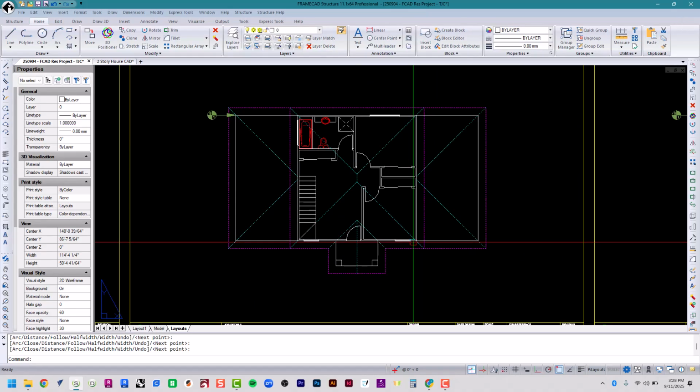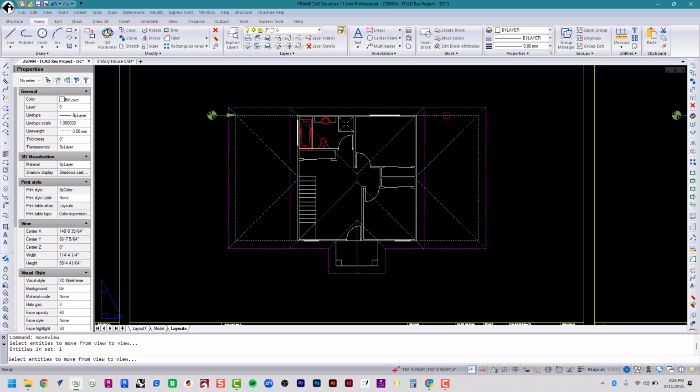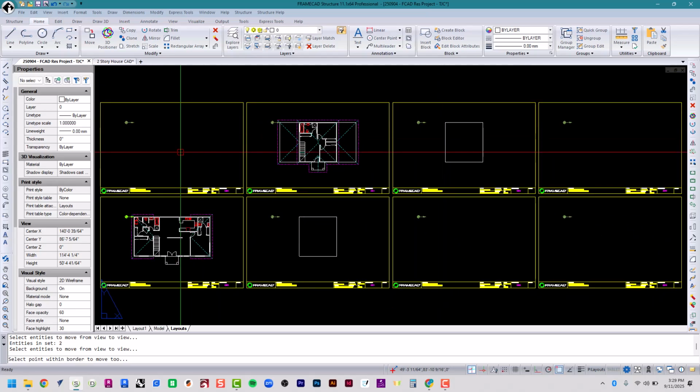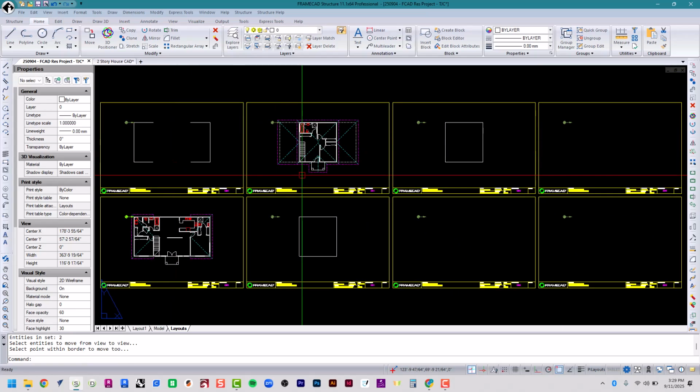Okay. Now the next thing I'm going to do is move view. We did copy view earlier. Now I'm going to type in move view. Oops, let's type it incorrectly this time. And I'm going to select that bracket I made on the left and the bracket I made on the right, and I'm going to hit enter. And I'm going to hit border number 2 to move it from border number 4 to border number 2.